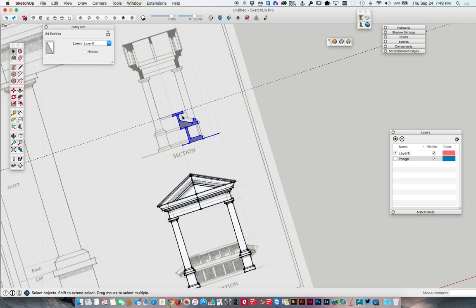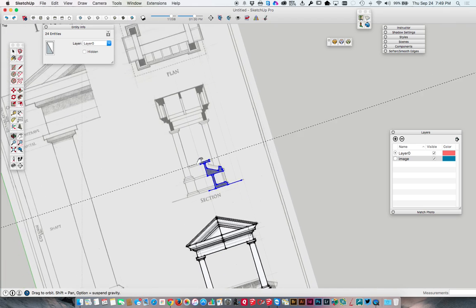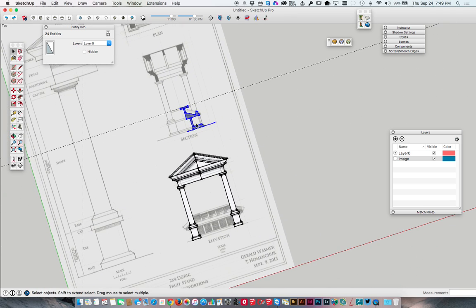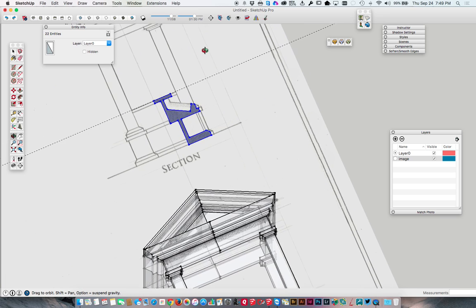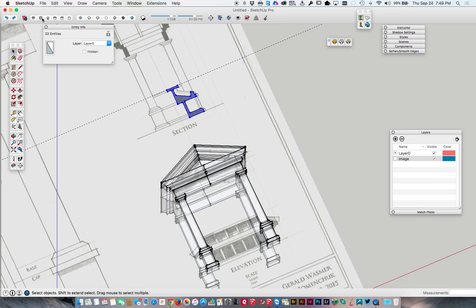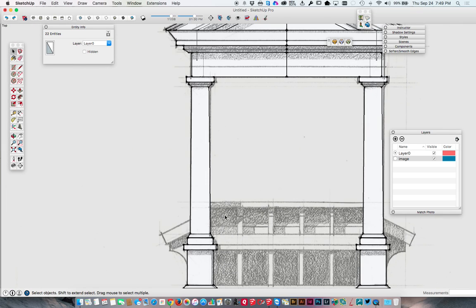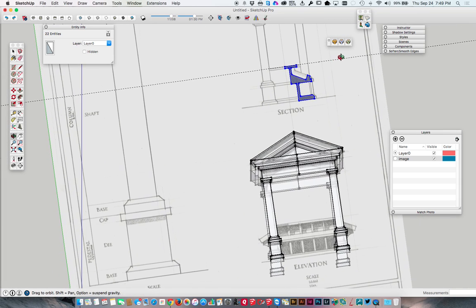I'm going to assume that this actually goes all the way around. This top part goes all the way around. I'm just going to do it on the front. I may not get to do this entire thing just for time. You're getting the idea here. So let's erase that and erase this. We'll grab our profile and we can extrude it, and let's go into plan and just find out how long we need to extrude this thing. Approximately, let's just do it 5 feet. If it runs into itself, that's okay in this case. So we'll just extrude it up 5 feet.